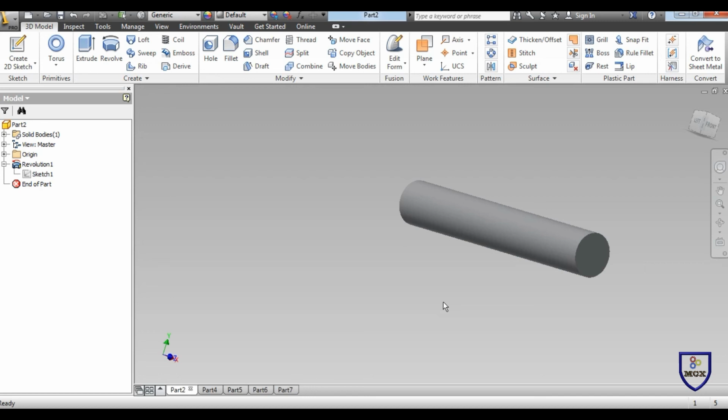Okay, so today in this tutorial we discussed the important 3D commands called extrude and revolve. For beginners these two commands are very important, so try to practice more objects, where we can do it either in extrude or in revolve. Maximum objects we can complete using only extrude. In some special cases a revolve command is required.